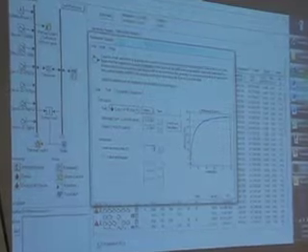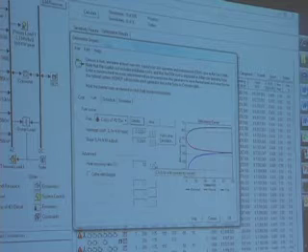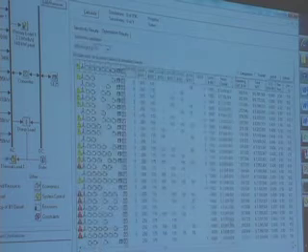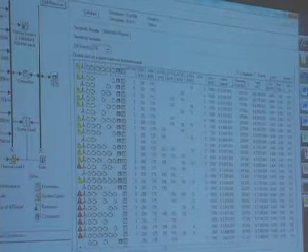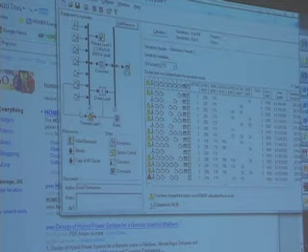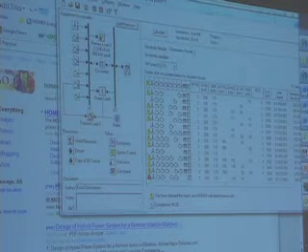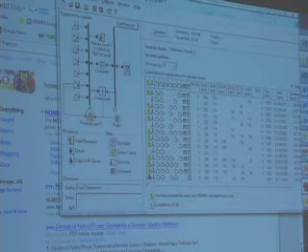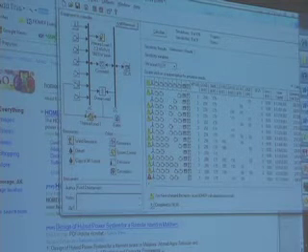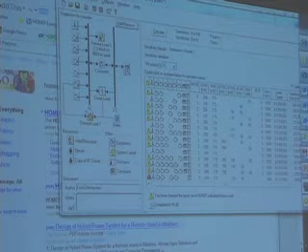If you put any number other than 0 in here, so let's say 50% of the waste heat from the generator can go to meet the thermal load, it does that. It calculates how much waste heat is generated by the generator, and 50% of that is available to meet the thermal load. And there very frequently will be excess thermal energy, and that's sort of normal.